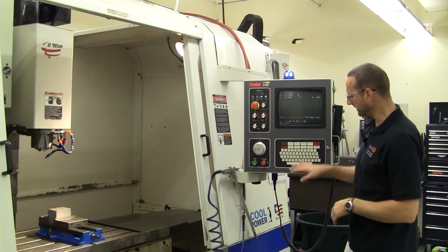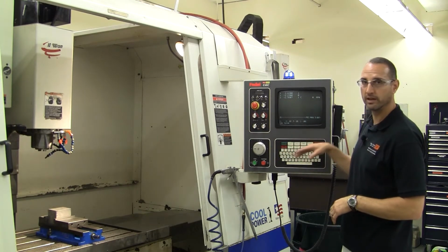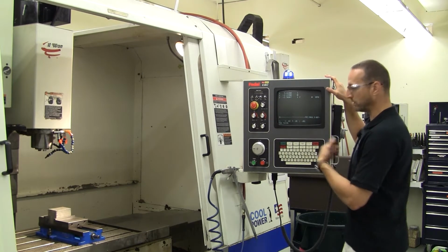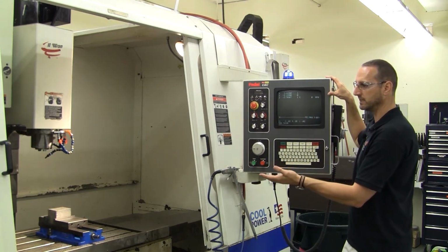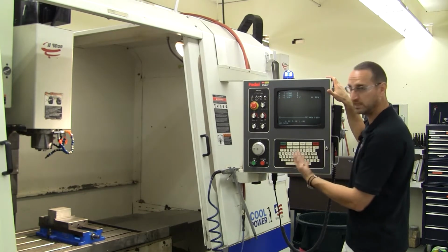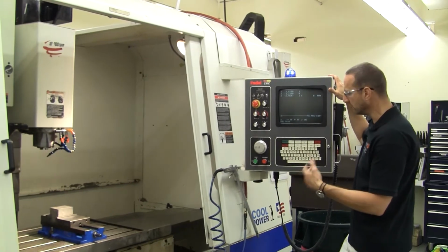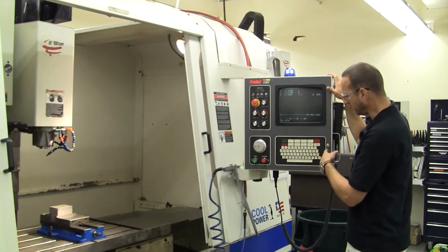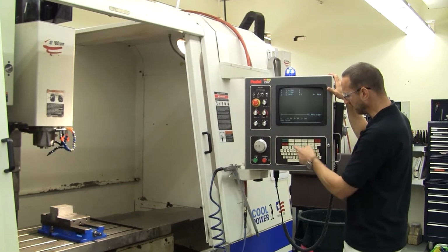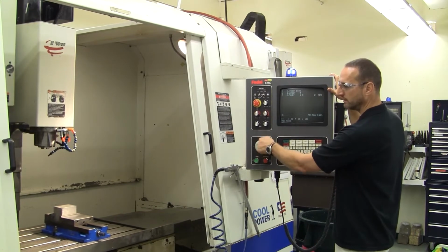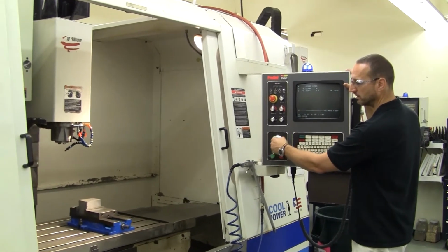I can also do it directly using the keyboard, and you have a few features here that are beneficial. If I want to change to a different axis to move, I can do that directly on the keyboard just by pushing the letter indicating the axis that I want. So for X, I just push X. You notice it changes right there. And if I want to change it to my large increment, I can push the H, and then now I'm back to moving the X axis and the handwheel is active.